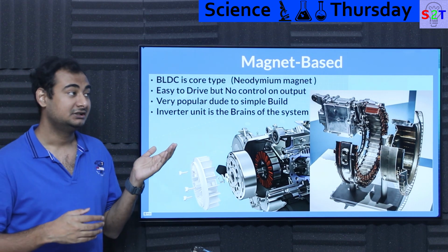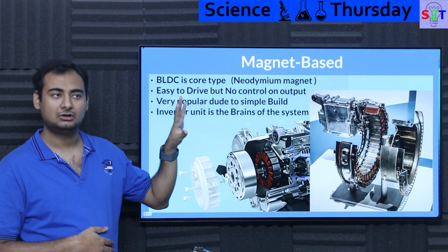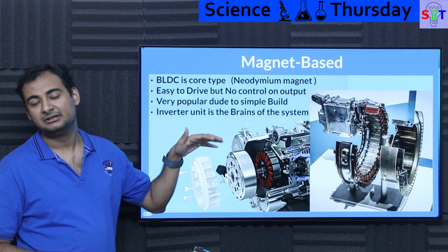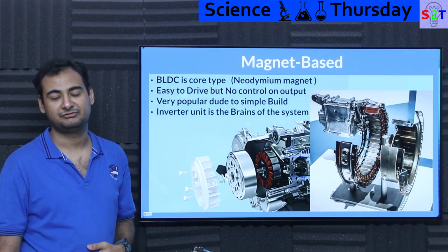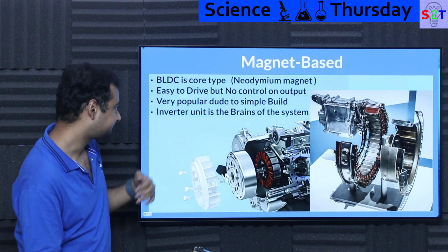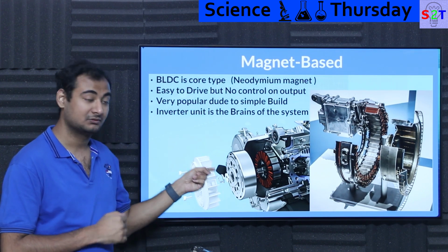In that sort of scenario, if your alternator had a permanent magnet, the voltage will go literally from, oh, I'm producing 12 volts at idling, 15 at mid RPM, and the moment you start to floor it, it will be like, yeah, I'm putting 50 volts into your battery and cooking it. So there is no control if you do not have electromagnets. That's the problem with BLDC.